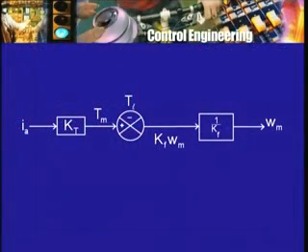So if I were only to look at that part of the block diagram, then assuming that Ia I have got somehow, I put this block Kt, so that produces what I had called earlier Tm, the motor torque. From this motor torque, once again this difference device, this circle, will make its appearance. From Tm I will subtract TL, and so the difference will be Kf omega m, and therefore the output will be Kf omega m. Once again, Kf omega m is not easily measurable physically.